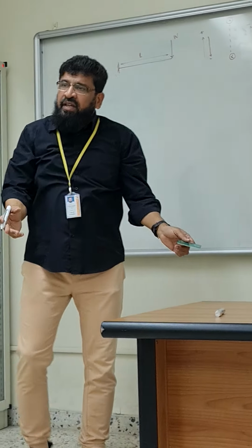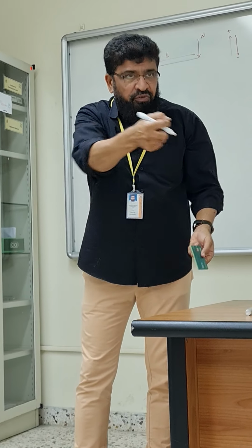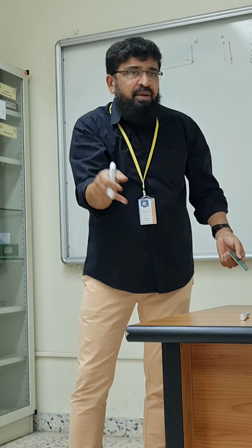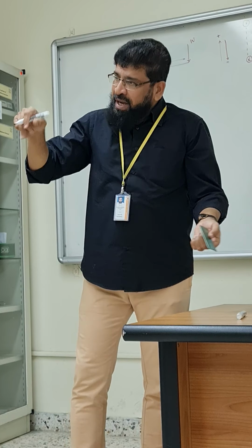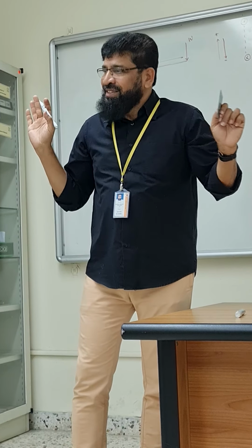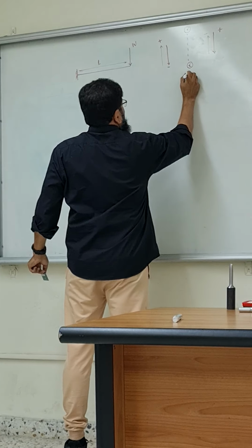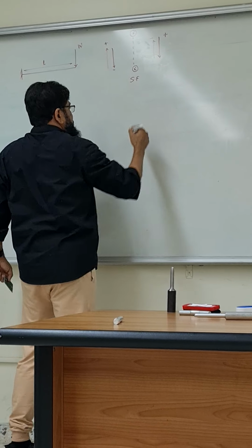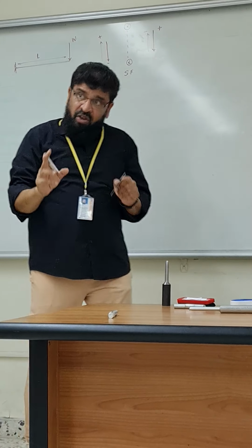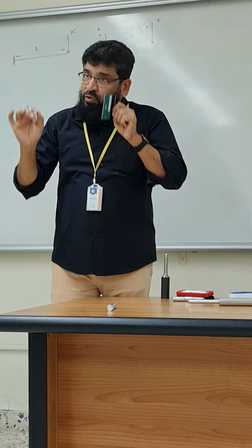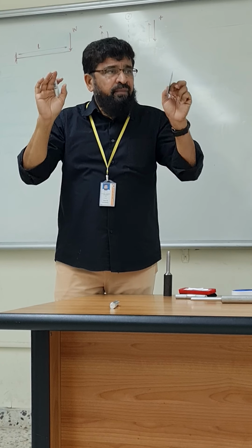There is nothing like negative 10 kilos. You have 10 kilos. If you take it after 10 kilos, it is 10 kilos. You cannot say minus 10 kilos. The minus sign is only showing you the direction. That's all. So this is the shear force, and this is the symbol for shear force. Before solving any problem, you first need to write the shear force sign convention.